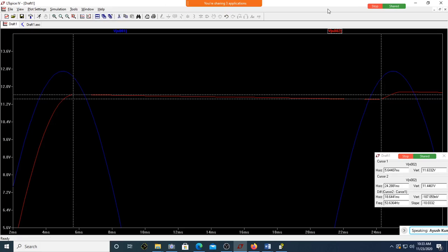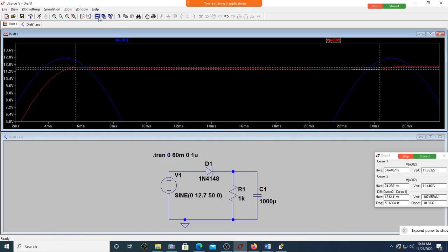This is not a big error in terms of voltages when you are dealing with rectifiers and regulators. This is fairly okay. In mathematics 2.5 is not equal to 2.3, but in electronics when you're designing something, this much approximation is allowed, especially for this rectifier circuit, because if the ripple is 500 millivolt more, there's not a big harm on your circuit.